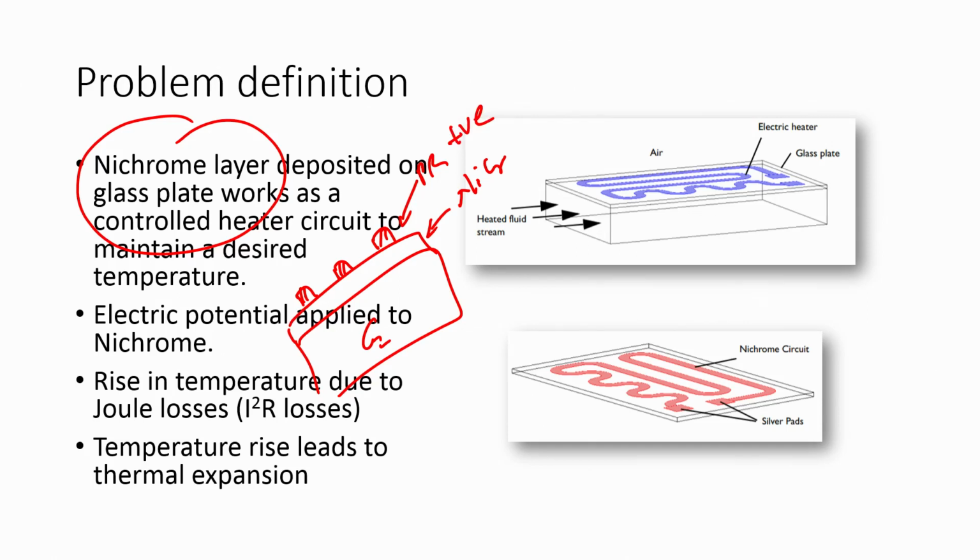Once you have this, you can dip this wafer in nichrome etchant. When you dip this wafer in nichrome etchant, what will happen? You will only have nichrome below the photoresist, and this is because the photoresist will act as a mask and save the layer below it.